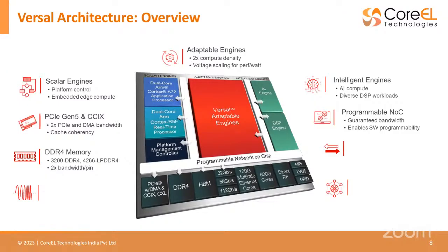So back in the 7 series architecture, what we have seen is that we are using dedicated RAMs, which are block RAMs, and distributed RAMs, which is also called the DRAM. And an extension over that was using UltraRAMs, which are meant for high-speed data storage applications. Then we also had DDR memories in some UltraScale parts.